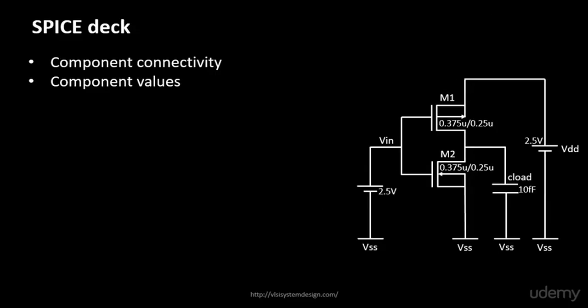Next we'll define the value of the input gate voltage. We'll assume a value of 2.5 volts. Generally, if you have a channel length of 250 nanometers, usually the voltage is kept in multiples of 250 nanometers, so in this case it's 2.5 volts. Had the channel length been 0.1 micron, this would have been 1 volt, and so on. It's just a calculation, and I'll get into the calculations in some time. For now, we'll assume a gate voltage of 2.5 volts. We'll assume a drain voltage or the main supply voltage as 2.5 volts, and we'll move on.